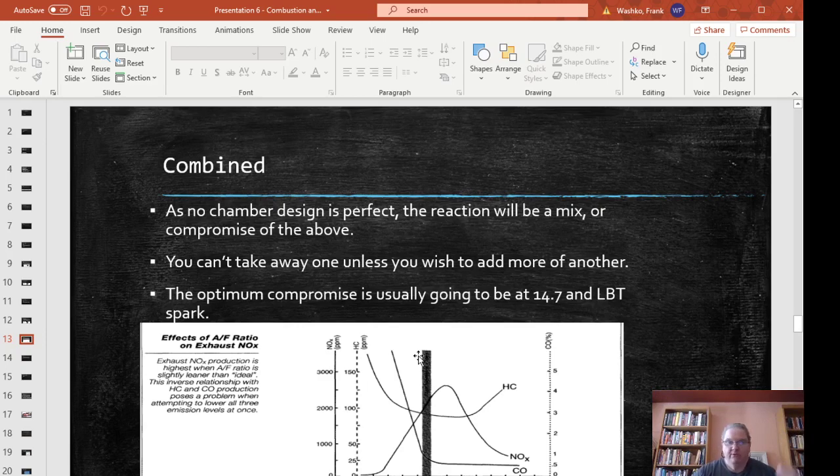And hopefully you've done a really good job of designing the chamber, and what's coming out is minimal anyways in terms of hydrocarbons, carbon monoxide, NOx, but whatever you do end up with, you can deal with in an after treatment in the exhaust after the exhaust valve.